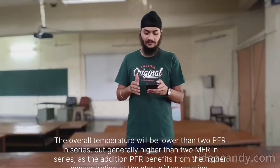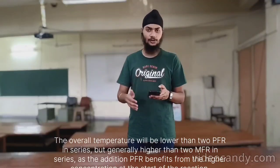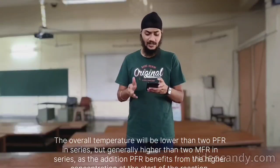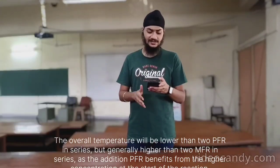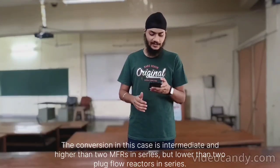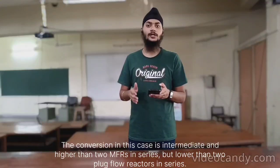The overall conversion will be lower than 2 PFRs in series, but generally higher than 2 MFRs in series, as the initial PFR benefits from the higher concentration at the start of the reaction. The conversion in this case is intermediate: higher than 2 MFRs in series, but lower than 2 plug flow reactors in series.